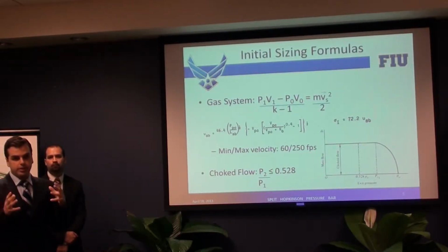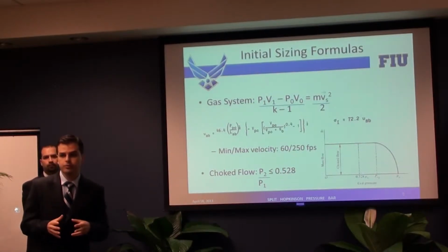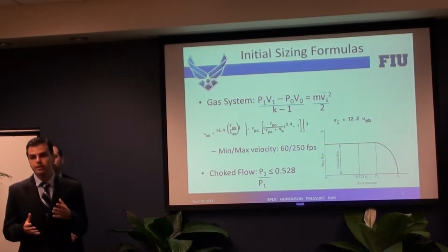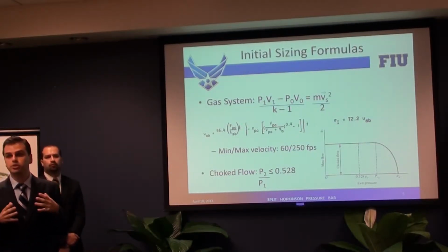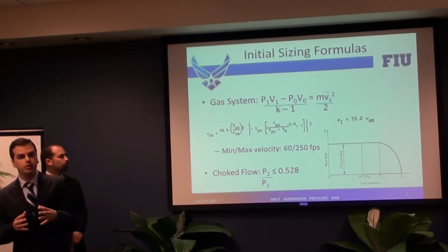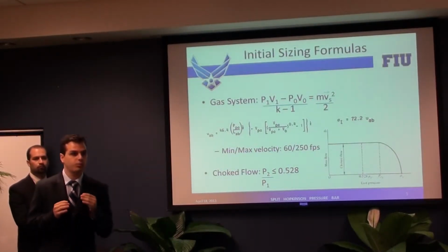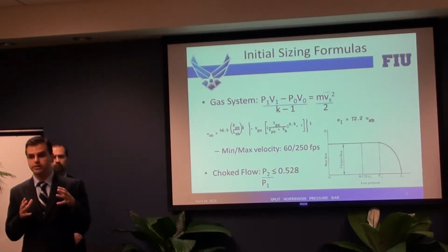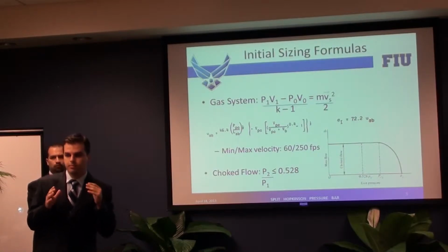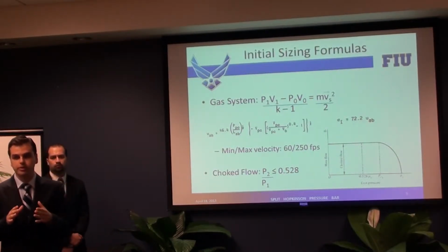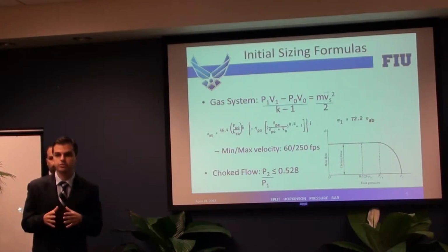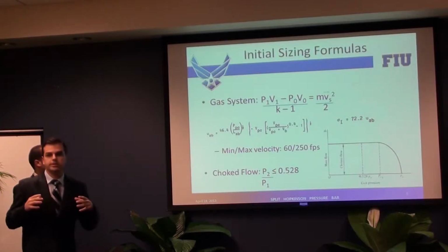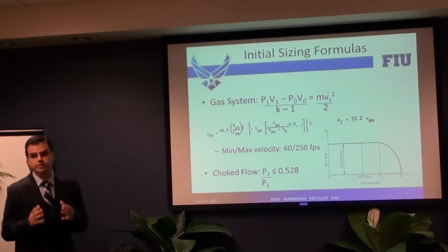Since we are using a valve, the speed of the compressed gas after the valve will approach Mach 1. This will cause us to encounter a phenomenon known as choke flow. Choke flow means that no matter how much mass we put into our system, no matter how much pressure you put into our tank, we cannot pump more mass past a certain point through our barrel because we have compressed the gas to its full extent. So what we did was that we increased our diameter size.